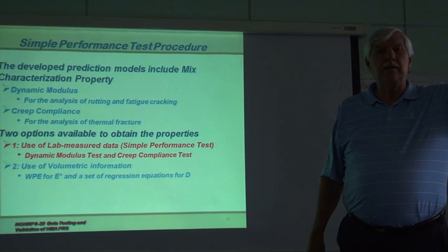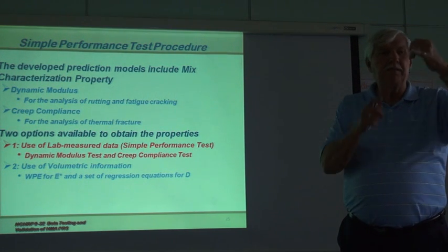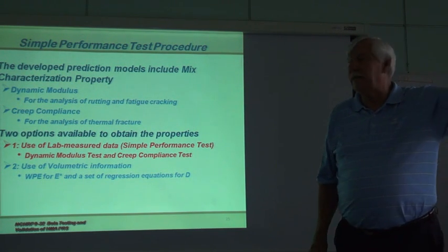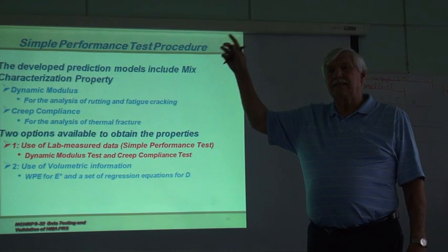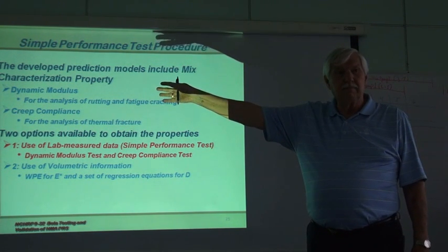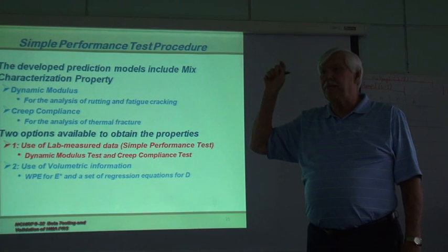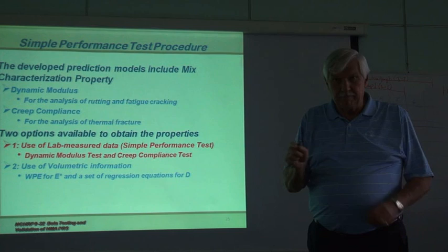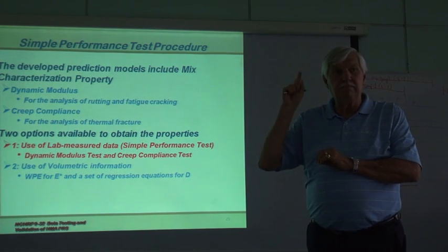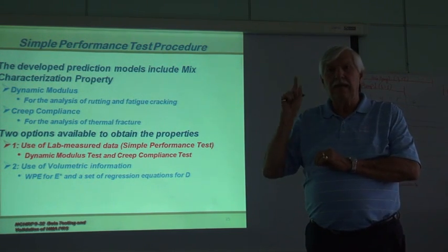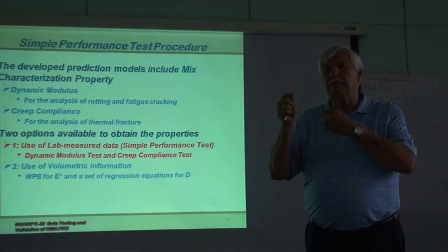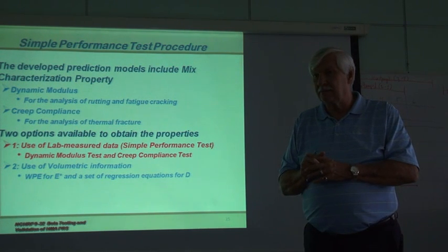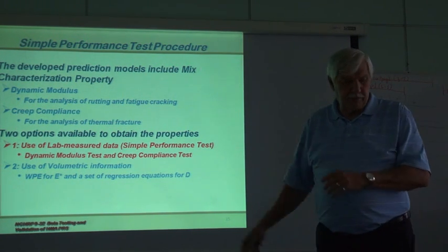So what we're saying now is, number one, the E-Star test is by far the most important. How do I get that? I can do it one of two ways. I can measure asphalt content, air void, gradation, plug it into the predictive equation, go into the QRSS and do a design and see the life. Or I can take my effective temperature, the effective frequency, and go to the laboratory and measure the E-Star value at this one critical point and compare it to the E-Star minimum that we would need in the design process. So that's what is being pursued.